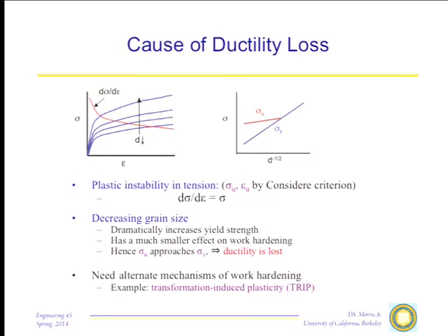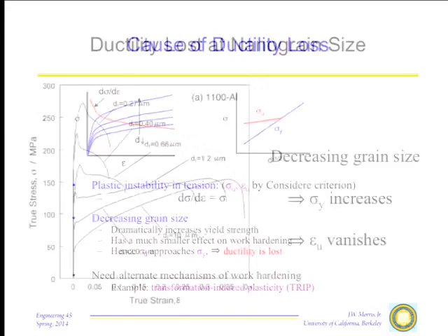This is the yield strength. This is the ultimate tensile strength. This curve actually comes from a much more sophisticated model. As a function of the grain size, as the grain size gets very small, the yield strength increases. The ultimate tensile strength also increases, but not nearly as fast, so the two eventually coincide, and the material is effectively brittle. And you see that happening here.